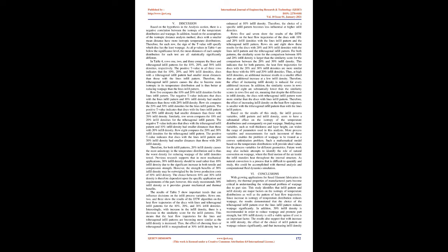Similarly, row 7 compares the 10% and 20% infill densities for the trihexagonal infill pattern. The negative t-value indicates that disks with the trihexagonal infill pattern and 10% infill density had smaller distances than those with 20% infill density. Row 8 compares the 20% and 30% infill densities for the trihexagonal infill pattern.